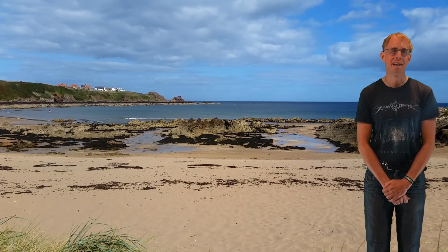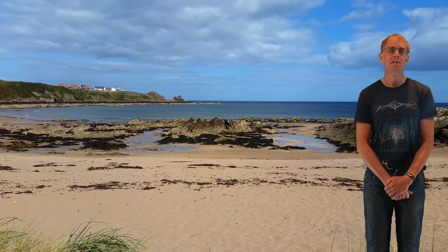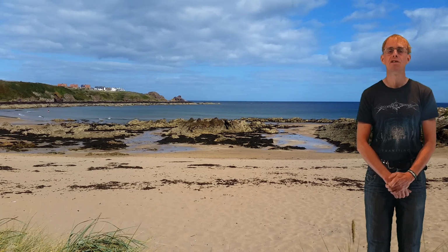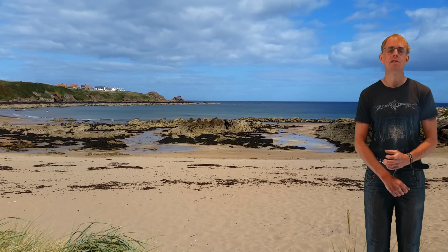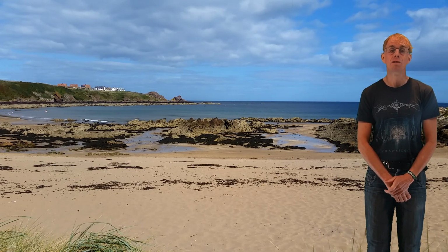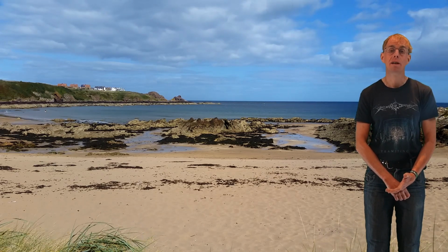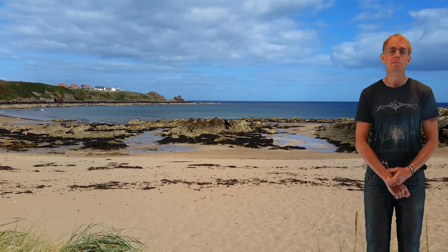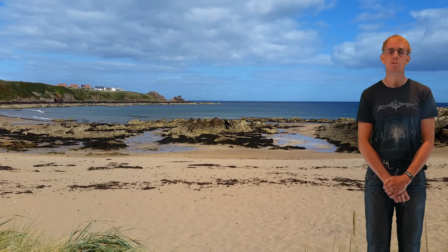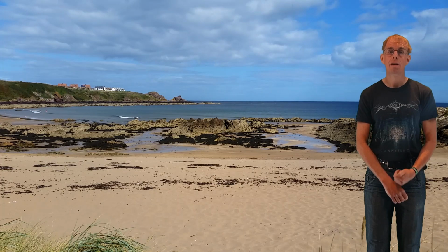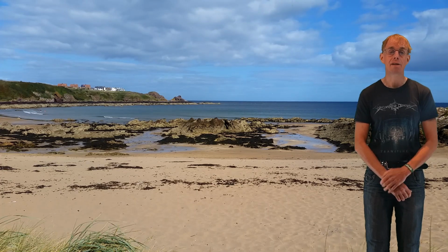Hello and welcome to Lesson 3. This lesson is going to examine the topic of generalised Newtonian fluids. That is to say, fluids where the viscosity depends on the shear rate of the flow rather than being constant. We're going to examine three different generalised Newtonian models: the power law model, the Carreau-Yasuda model and the Eyring model.